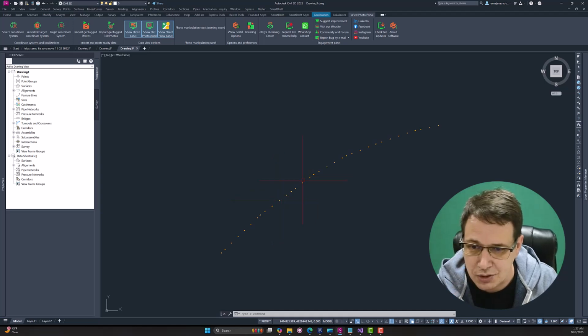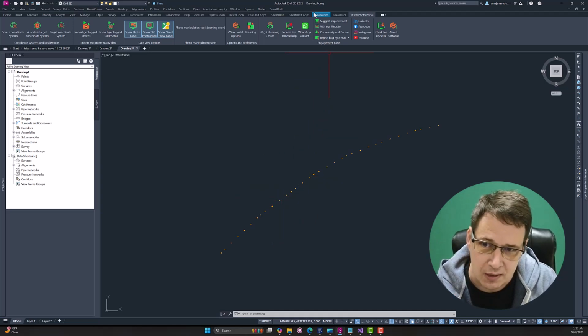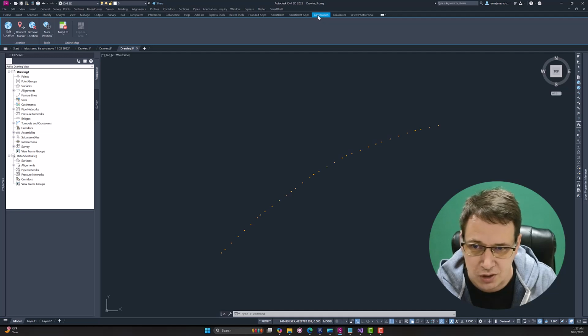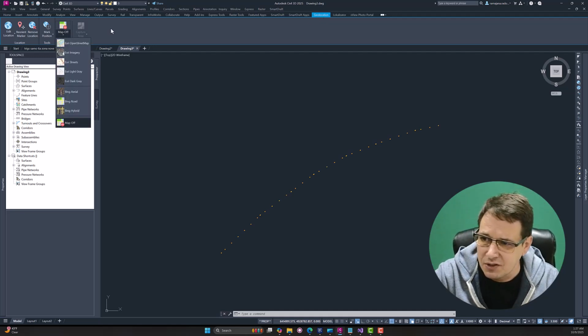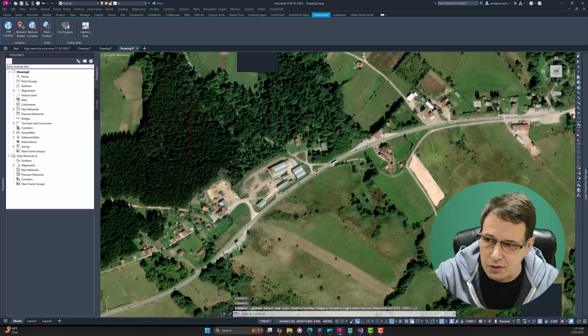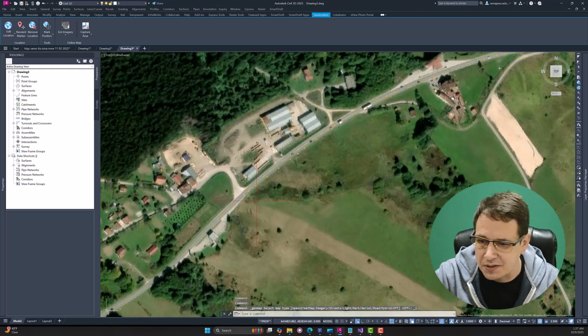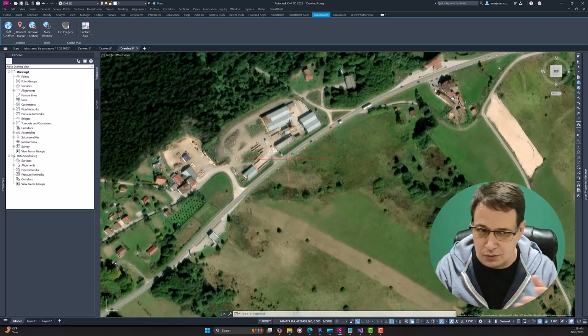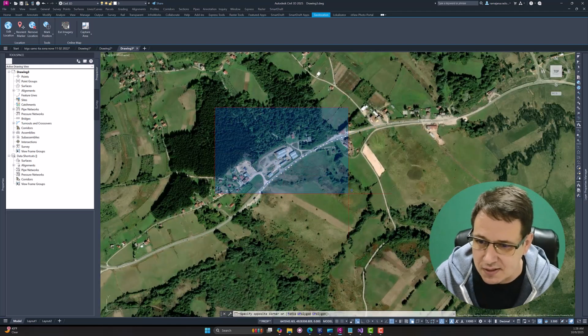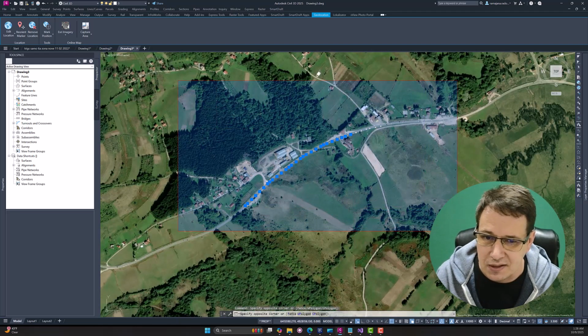What I was telling you is actually this part, because when you set the coordinate system for the Autodesk DWG or DXF files, you get this geolocation contextual ribbon menu. This ribbon is based on just a few functionalities, and one of them is to turn on base imagery data. In this case, I just turned on Esri imagery, but as you can see, it's interconnected between the AutoCAD coordinate system and the coordinate system of the data that I imported.